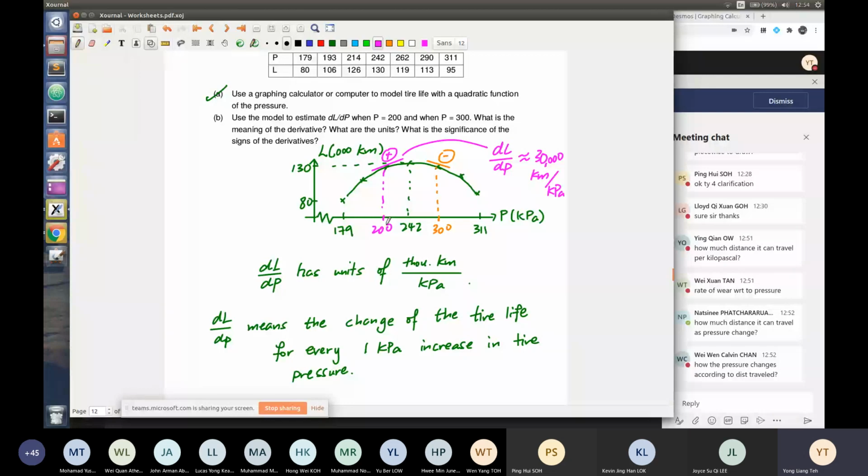As a mechanic, let's say I know that the client only pumps at 200 kilopascal. So 200 kilopascal is actually not wrong. Of course, it's not ideal, but it's not wrong because maybe he wants his car to feel softer. When you have a lower tire pressure, your car actually feels softer, and usually quieter. So therefore, it's a more comfortable ride, not as so-called jumpy.